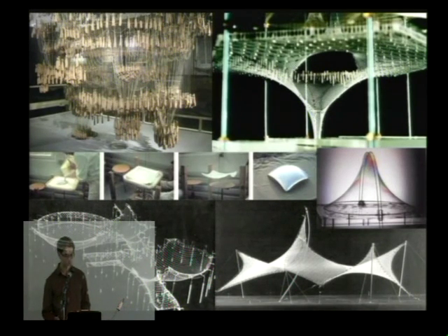Originally this was done a lot through physical models with soap films and hanging chains, because the thing about making a form in response to the forces is that you change the form according to the force, and then the forces change and you have to loop through, which can be difficult to do through straightforward calculation. For a while these actual analog models were really the only practical way to do it.